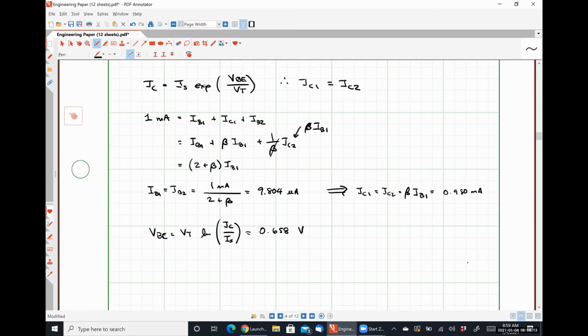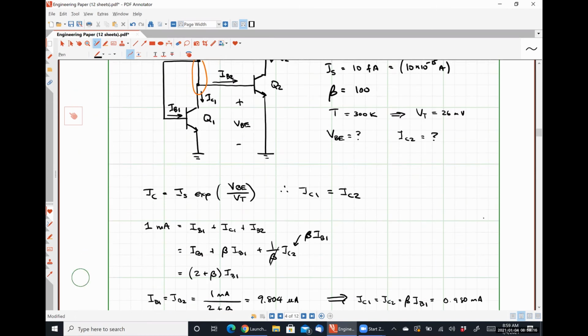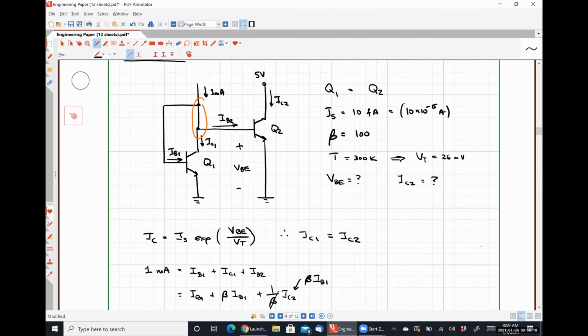This configuration is what's called a current mirror. And so we see that whatever current is flowing through the collector of Q2, that same current must flow through the collector of Q1, and we could actually hook up more and more. That's a fundamental building block of making large-scale amplifiers with BJT, which is something we'll get to later, but we're kind of introducing at least a little bit how it works now.